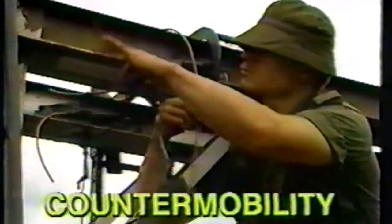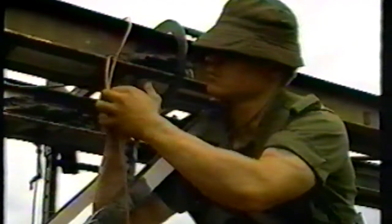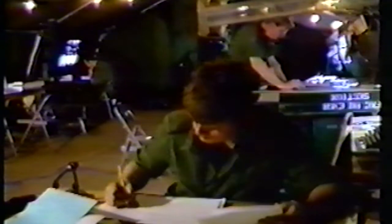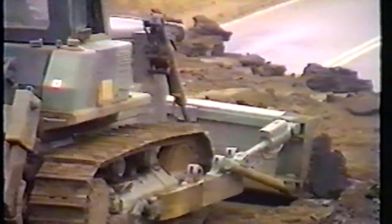Counter-mobility involves the reinforcement of terrain or the creation of artificial obstacles to delay, disrupt, or kill the enemy. It encompasses planning, construction, and the logistic and transportation efforts associated with its accomplishment. Counter-mobility tasks mainly include point targets, such as road craters, abattis, rubbling, mining, and demolitions of bridges, utilities, or facilities, and linear targets, such as anti-tank ditches, minefields, and routing.